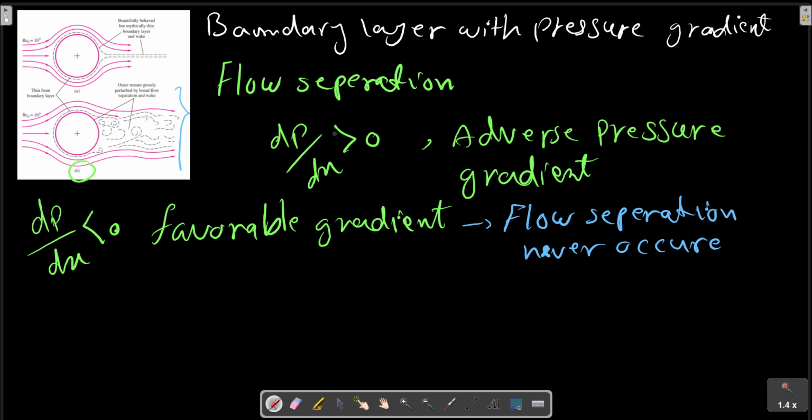We can explain flow separation with a geometric argument about the second derivative of velocity u at the wall, from the momentum equation at the wall. For a boundary layer we have derived a relation before.